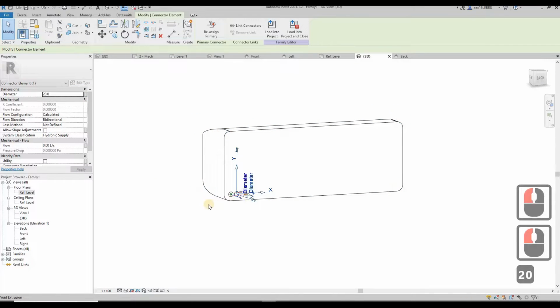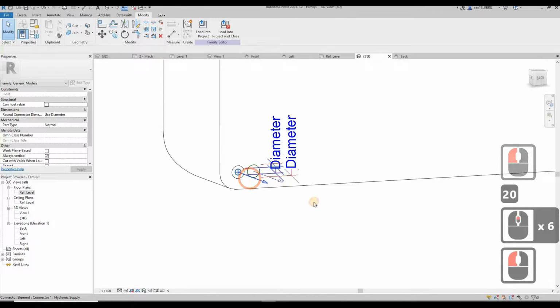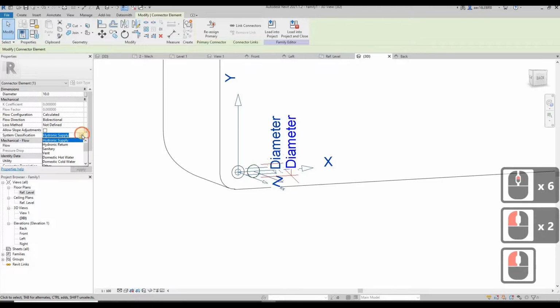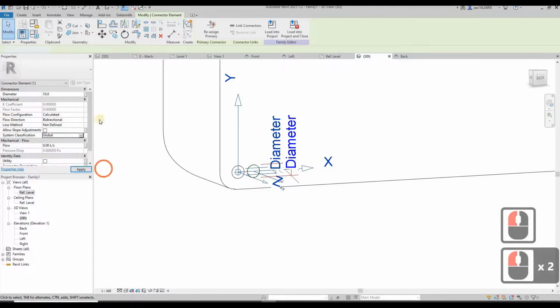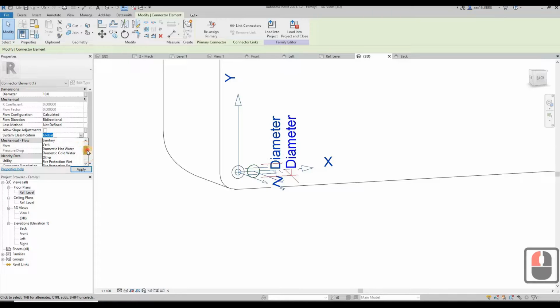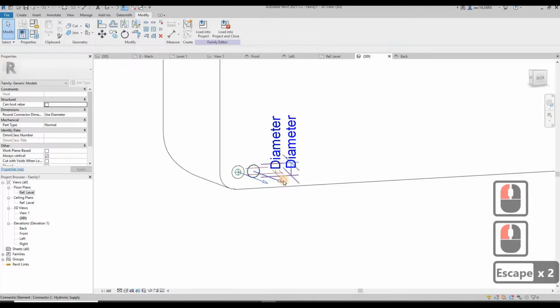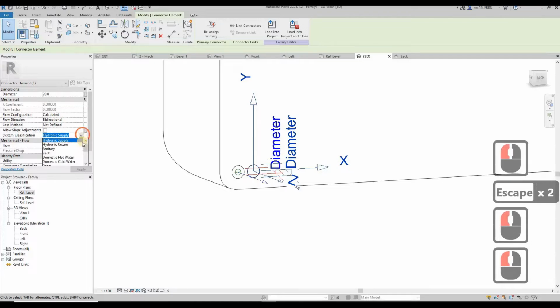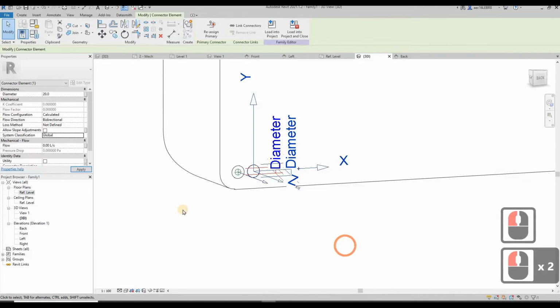Okay, so you're going to assign this as a system here. You're going to assign this to global because you're not sure what the system type is. Although you know that this is for refrigerant, it's not stated in the list here. You just temporarily put it as global. Okay. Then the next thing is this is drain. Of course, you don't have a drain system mentioned here. You just put it as global also. Okay.